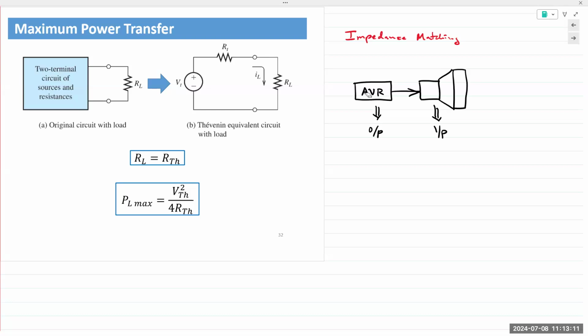A very simple analogy can be made in terms of vehicles. Whether your vehicle is gas powered or an electric vehicle, let's say you pump the pedal or pump the gas and accelerate very, very quickly. What are we doing? We are burning a lot of fuel, whether we are using up stored battery energy or gasoline or diesel, to get a lot of power. So maximum power is transferred, but it's not at maximum efficiency.